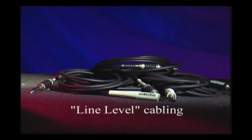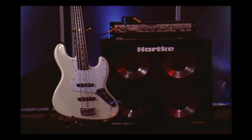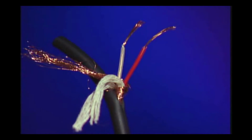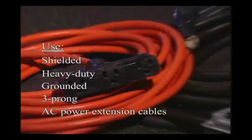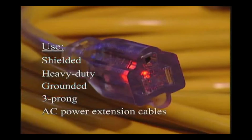The next type of cabling is line-level cabling, such as cables used to connect instruments to amplifiers or cables used to connect system devices to the mixer, such as effects or dynamics. Here again, whenever possible, use balanced cables. Balanced cables provide the maximum flexibility for arranging an effective grounding scheme. Next is power extension cabling. Always use shielded, heavy-duty, grounded 3-prong AC power extension cable to extend a power line if you're limited in available circuits and need to draw as much amperage as possible.